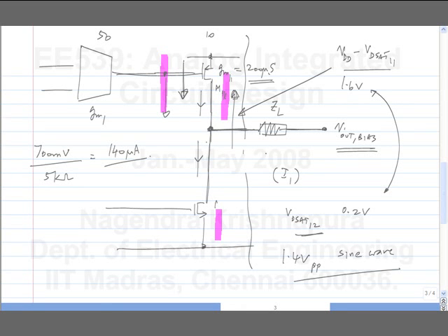Similarly, if the load capacitance increases, the current will also increase. Or if you have everything the same, but you need to scale it up to a higher frequency, then for the given load capacitance, you have to push more current. Then the current in the output stage increases. This is how you go about designing the output stage. I think you already have most of the parameters that you need. You bias it around 150 microamp, make sure that it has a GM of 200 microsiemens, and you connect up everything, it should work.